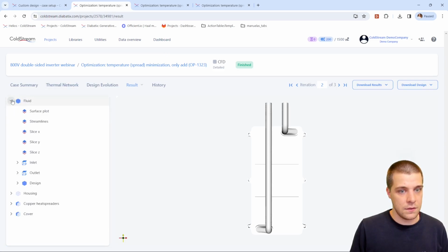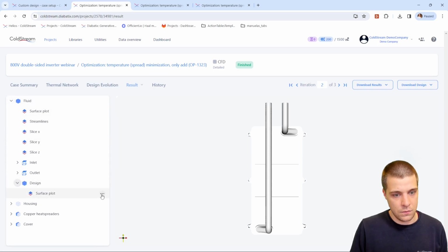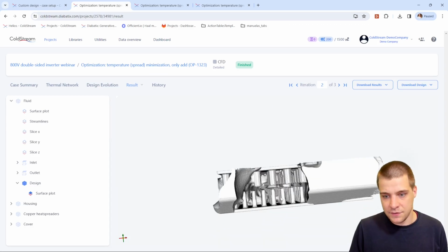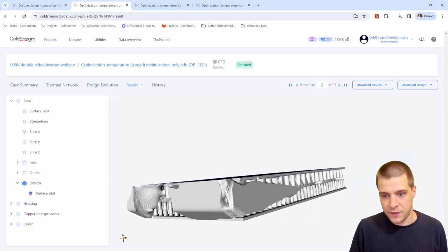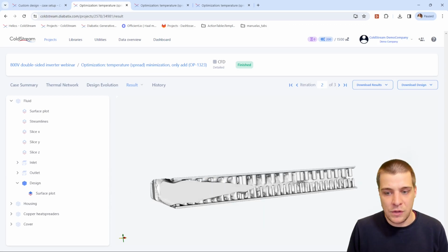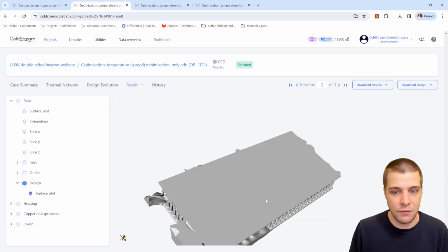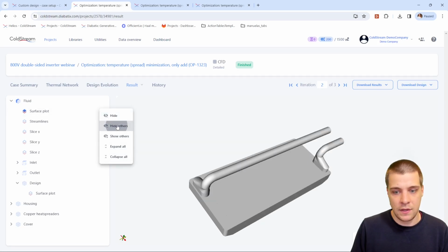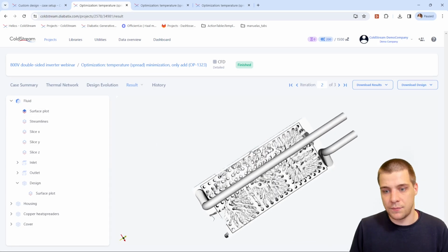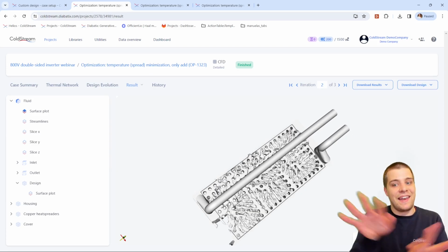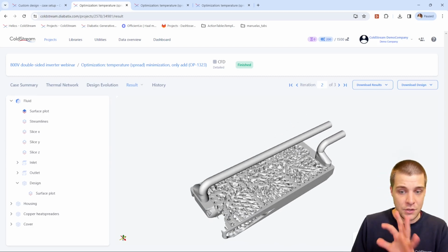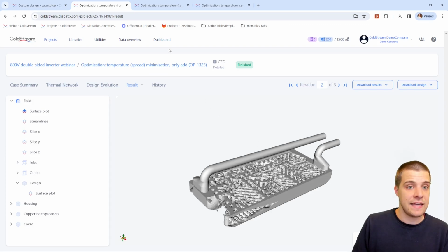If you only look at the add option, I will show the solid structures that ColdStream added. So the pins themselves, you will see they're all still present, and it's added material in between the pins to basically create bigger structures out of it. If you have a look at the negative, our remaining fluid, we will then see what ColdStream did. It's made a bit more of a spaghetti in between those solid structures. So this is an example of an only add case.